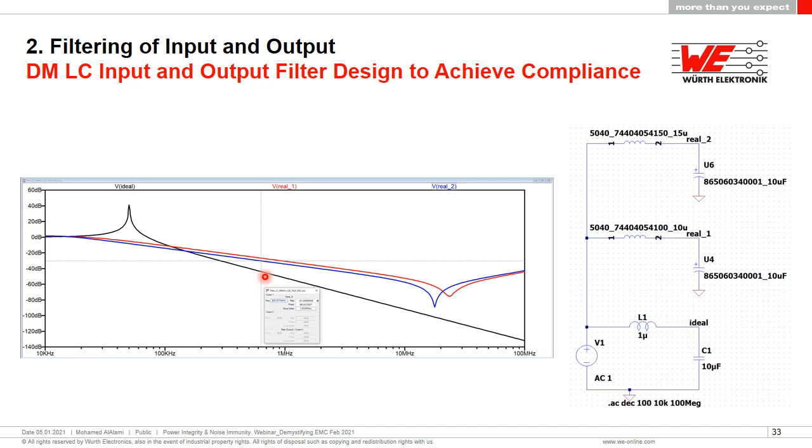Now, that's not necessarily the best of solutions. We have gone with this at the time, but there is also, of course, the opportunity to introduce either an MLCC here or to introduce a polymer there if we need a fairly high value of capacitance in order to improve things. I would be reluctant to start increasing inductance because of the current side of things.